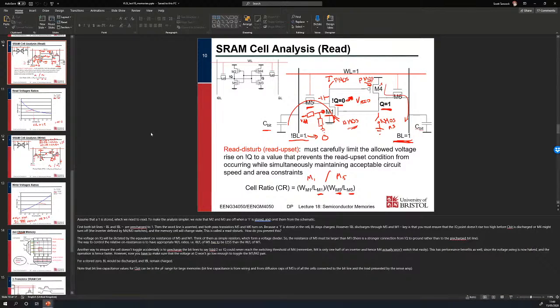So the better way to describe it: imagine an SR latch where you're overpowering the feedback loop between the S and R stages, and imagine them tightly packed in a grid, so you use pass transistors to access it. That's effectively what we've got. But it's definitely not a flip-flop at the very least, because there's no clock signal here as such.